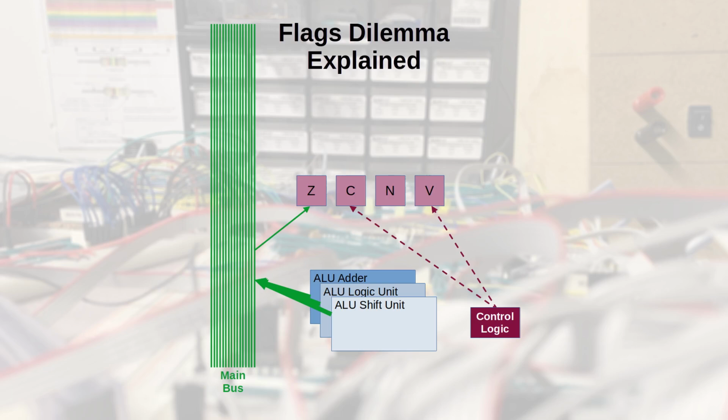The C flag, being just a 17th bit in some calculations, will be multiplexed with a 74HC151 IC. Simple enough to handle. It's overkill for the 8 bits that it can multiplex, distilling that down to just 2.